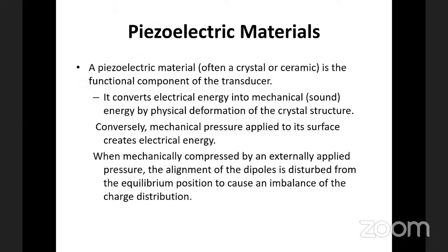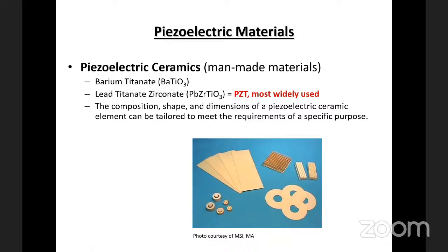Piezoelectric materials are functional components which can convert electrical energy into mechanical energy by physical deformation. When mechanical pressure is applied, its surface creates electrical energy; mechanically compressed by an externally applied pressure, the alignment of the dipoles is disturbed from the equilibrium position, causing an imbalance of the charge distribution.